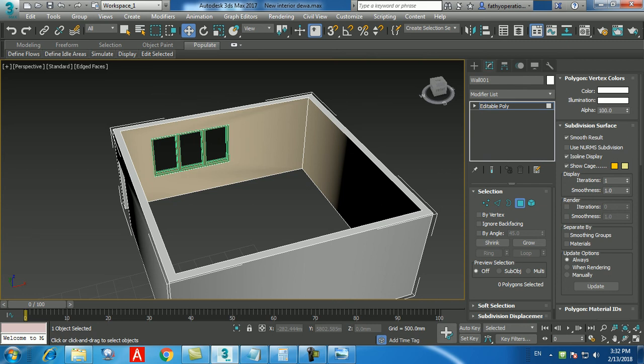If you want to select different colors for different walls on the same object, go to polygon, select it, then go to the Material and choose a different slot. We need to choose a polygon for one wall and apply different materials. For example, you don't want the same color near the window. Choose another color. It will not double.